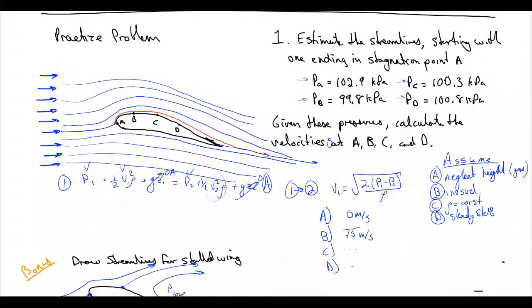lift, even here you have a low pressure. All the lift is generated by having a high pressure on the bottom and a low pressure on the top. By the way, what that high pressure on the bottom does is it pushes air down, and the low pressure pulls air down. So there's lots of ways of thinking about why an airplane generates lift. You could say it's because it forces air down, but you can't force air down without having pressure differences. So the two are synonymous.